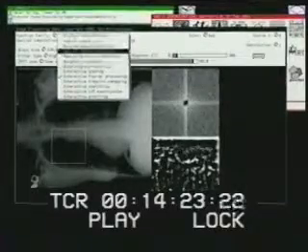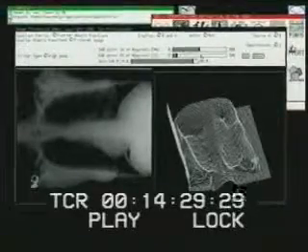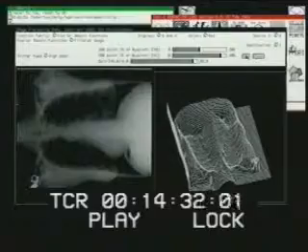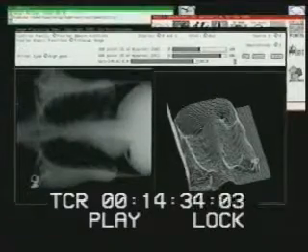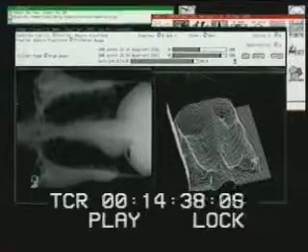If we like, we can go ahead and do the full 512 squared FFT, high-pass filter, and inverse FFT. It takes about 3 seconds to do a 512 squared FFT, and so this total operation will take roughly 7 seconds.